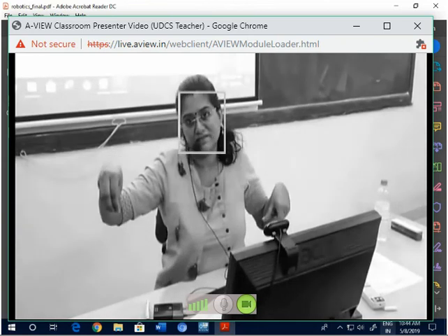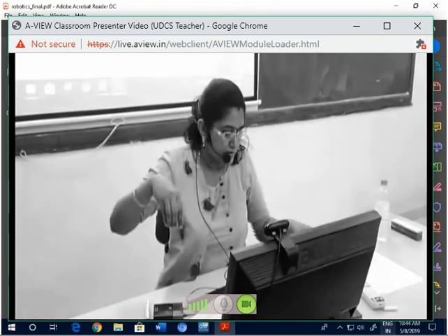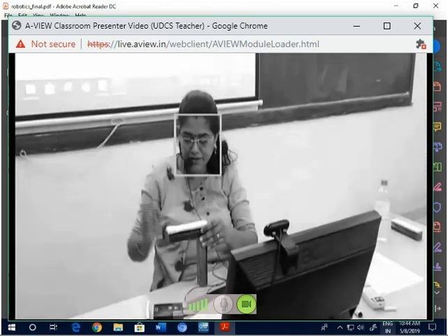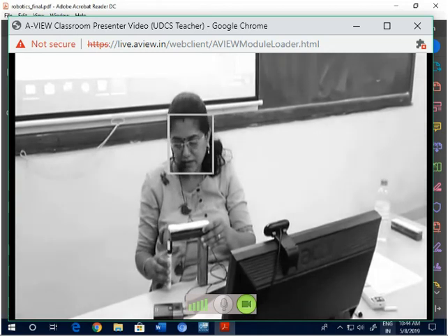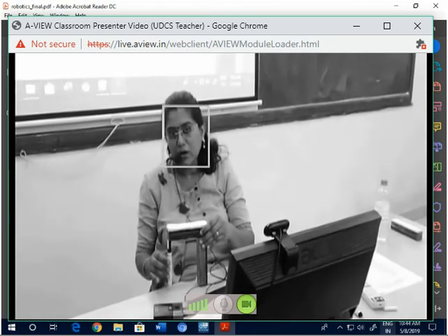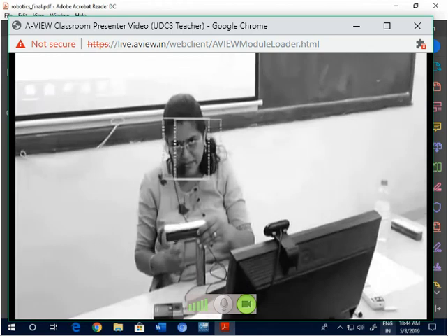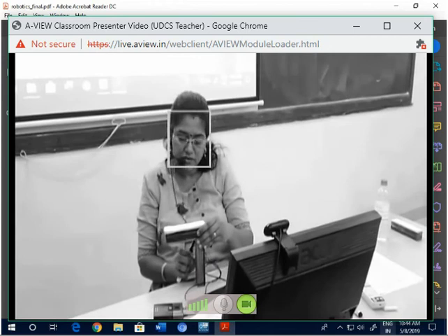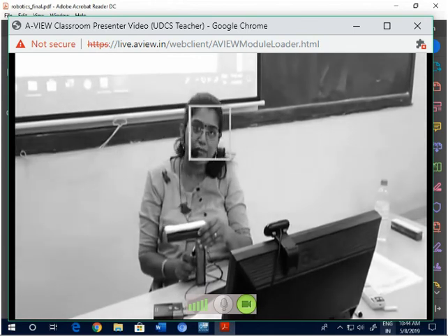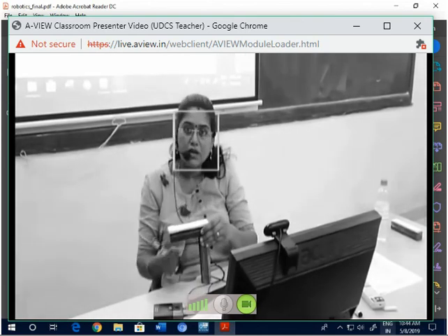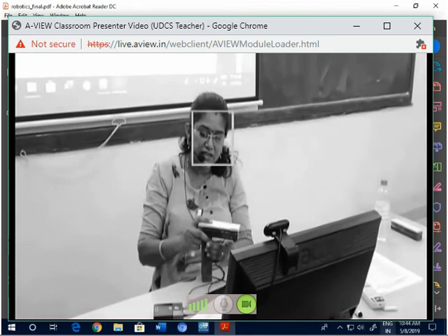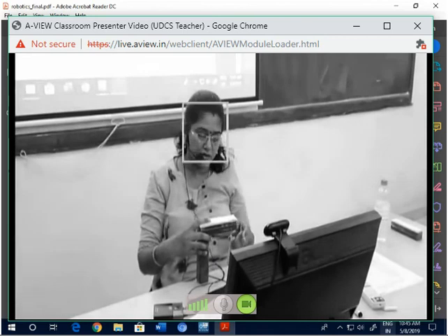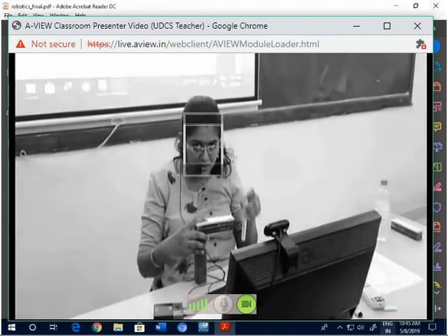Okay, suppose this is the base and this is the shoulder, elbow joint, and here is a tool tip. Fine, assume this to be the tool tip. Now, because the base is rotated to the right hand side, the tool tip is here. Now suppose it has 360 degrees of rotation. So if it is rotated now, this will rotate from this end to this end and the tooltip will be on this side. So the position of this tooltip, point P, depends on what?